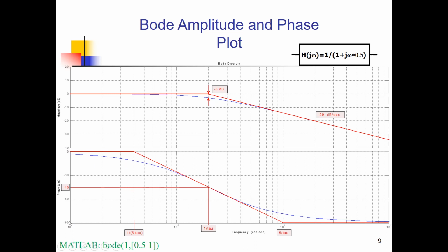Well, because it is 0.1, 0.2, 0.3, 0.4 radians per second, here, this point, and we put a dot at 5 times the crossover frequency, so it's 5 times 2, it's 10 radians per second, which is over here. And between these values and the phase at the crossover frequency, we draw a line from the low frequency phase behavior, which was 0 degrees over here, towards the high frequency behavior over here.